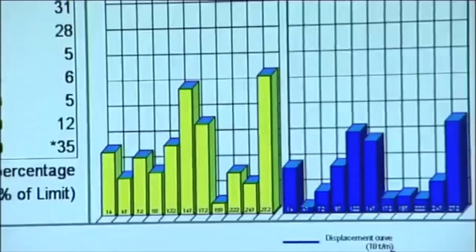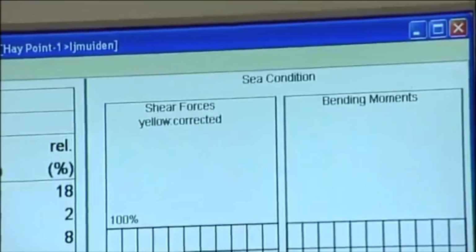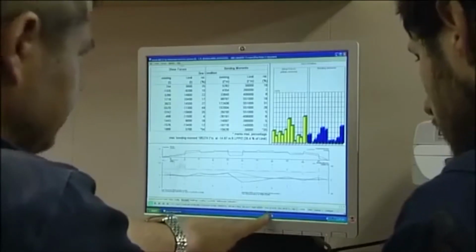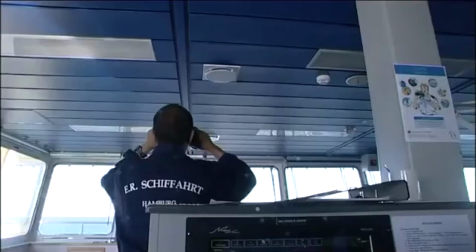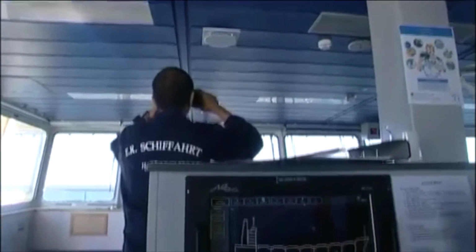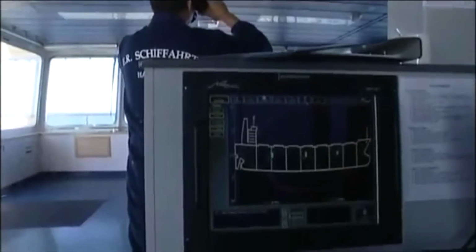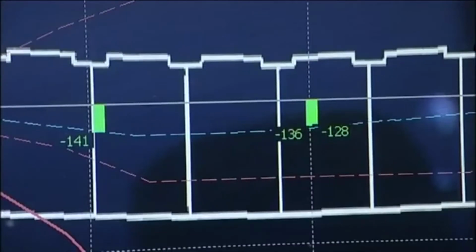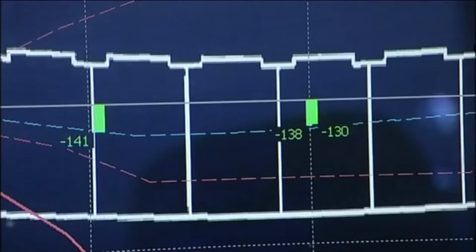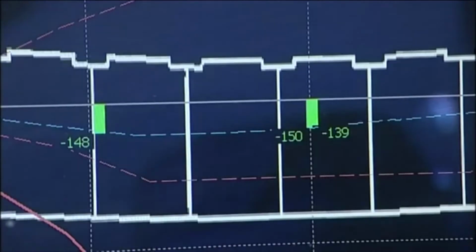And if plans deviate for whatever reason, the figures must be recalculated before acceptance. It's 54% maximum. Aboard some vessels, hull stress monitoring systems are fitted. These can provide ship's officers with real-time indications of the effects of shear force and bending moments, both at sea and in port. As they're often linked to the loading computer, they can highlight any deviations from the loading plan or the maximum permitted stress limits, allowing corrective action to be taken.